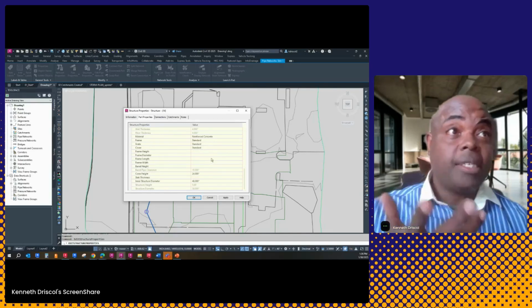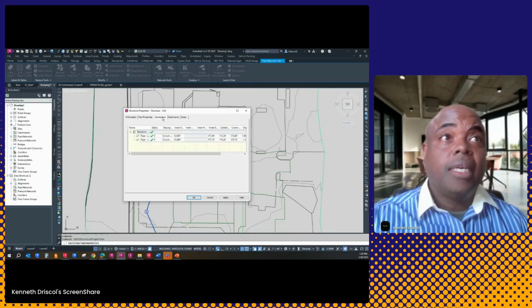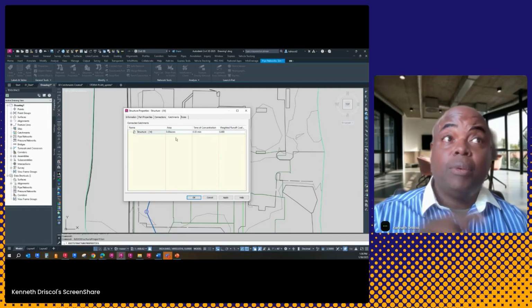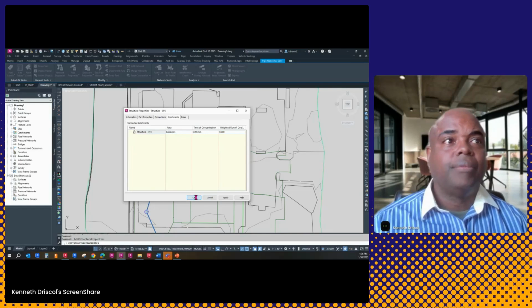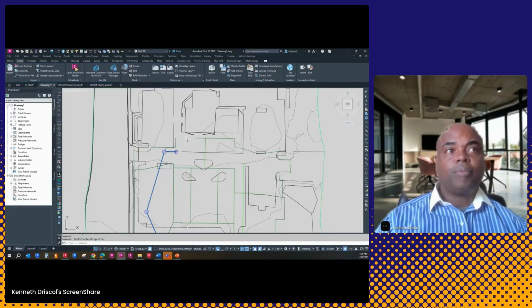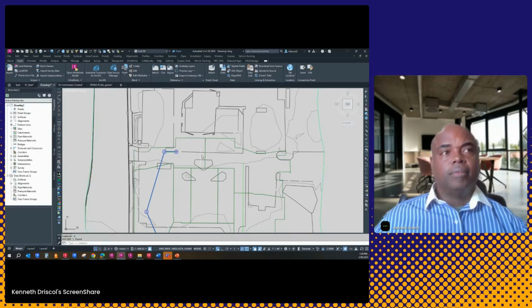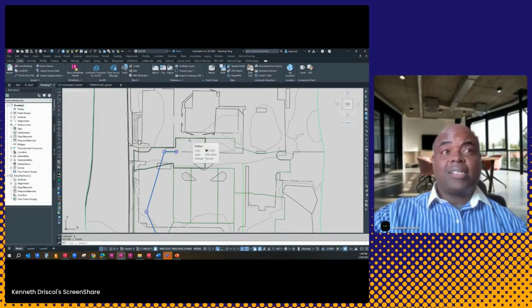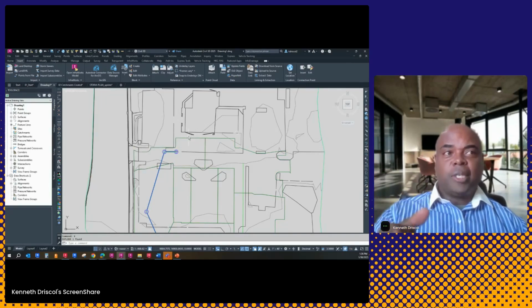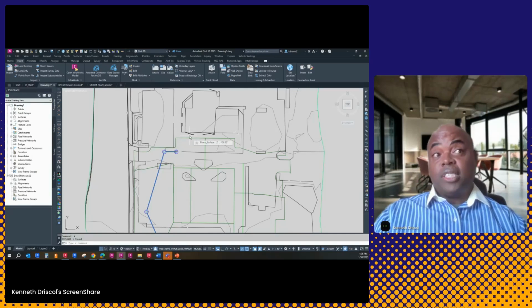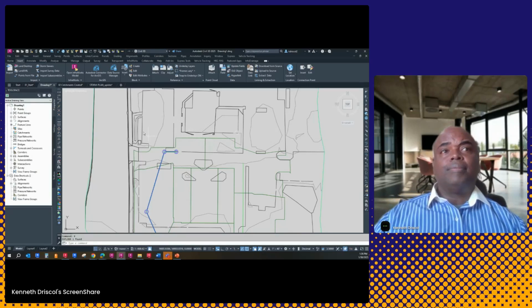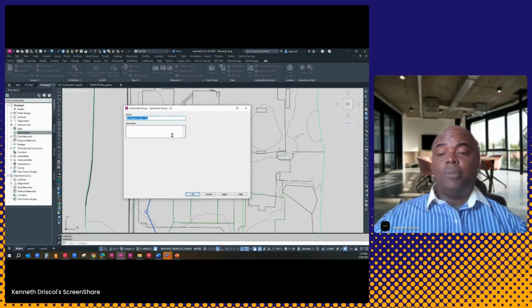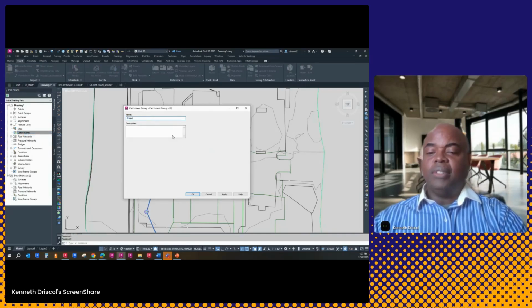Okay. So now we see some of these properties, and then the connections of these properties, and then what catchment. Well, so far, no catchment yet. But what I can do is, from this, and this part of this process, I'm going to minimize the time in terms of doing this because I can push this to InfoDrainage, and I'm going to do that so you can see the result of it. So under catchments over here, I'm going to create a catchment group. We'll say phase 1.